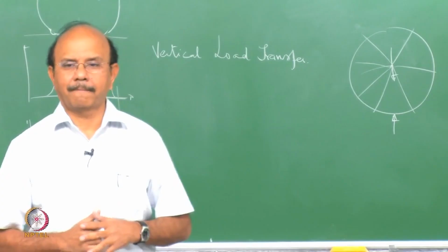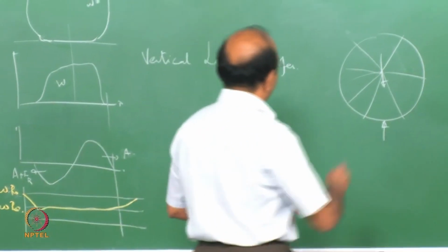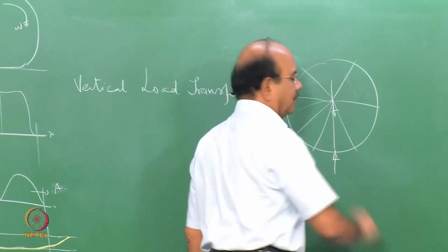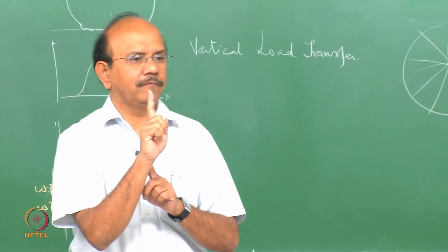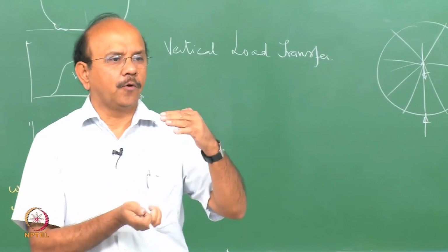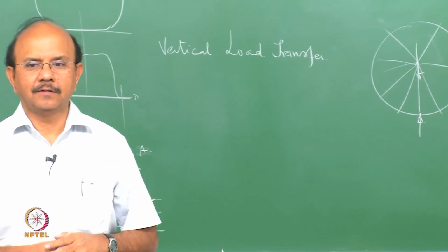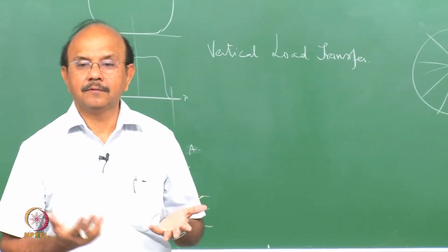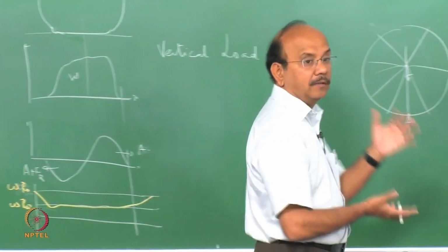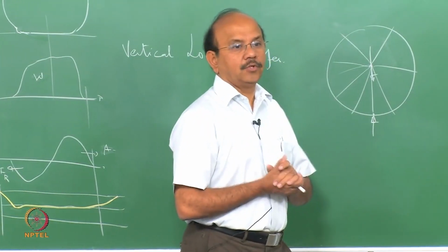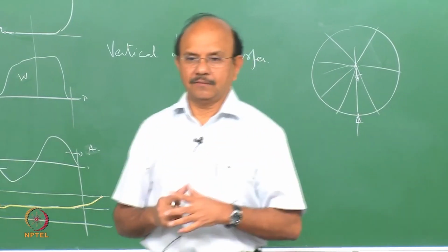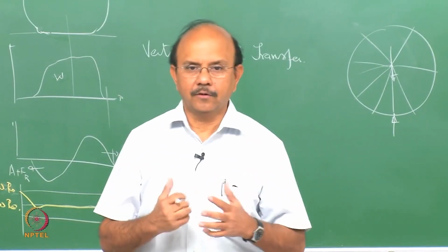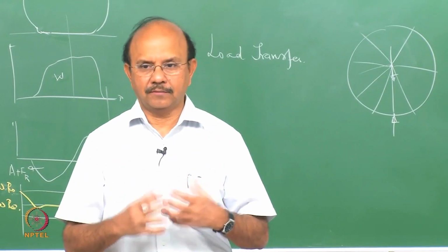Unfortunately, a lot more, because the spokes, as you know, is a very thin piece of steel. If you subject that spoke to compression, what is that that's going to take place? It's going to buckle. So the spokes are assembled with tension. They are going to be actually assembled with tension.